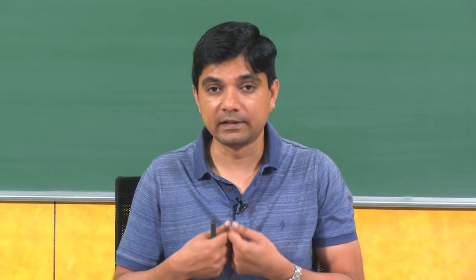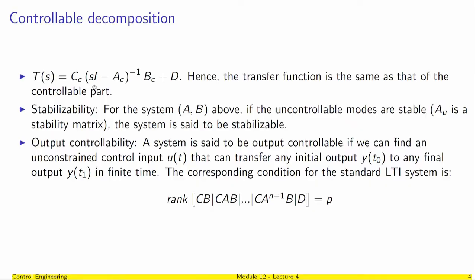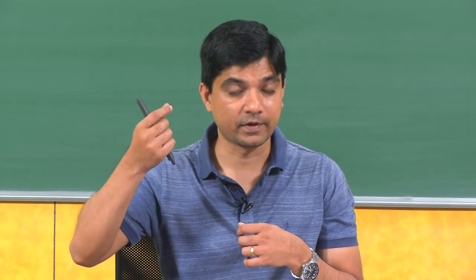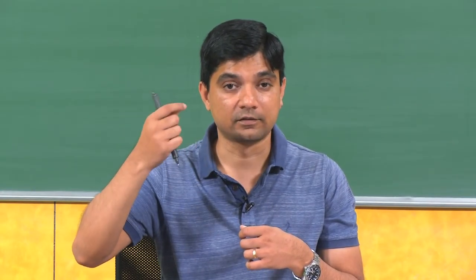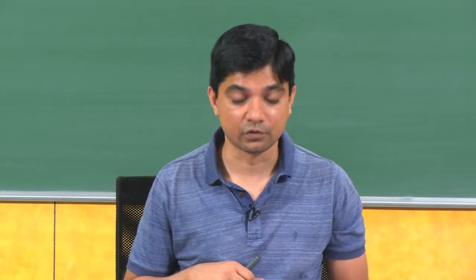Therefore, whenever I give you any transfer function, I could do anything with that transfer function if and only if I know that this is a transfer function of a completely controllable system. Otherwise, you see that some poles of the system go missing, or there is some kind of inherent pole-zero cancellation whenever the system is not completely controllable.